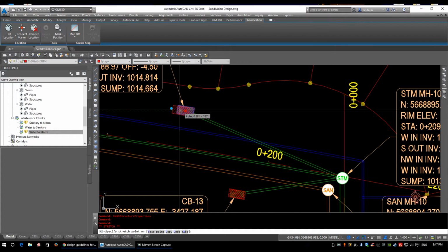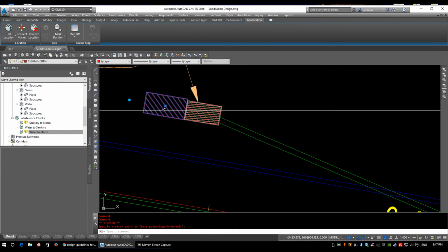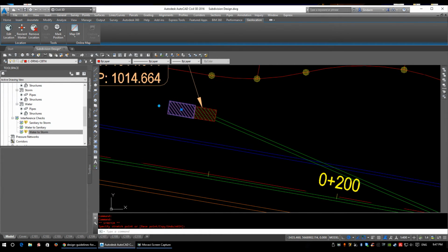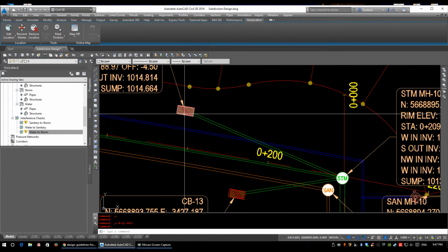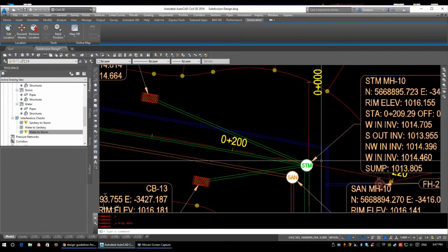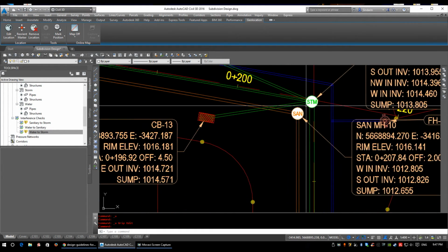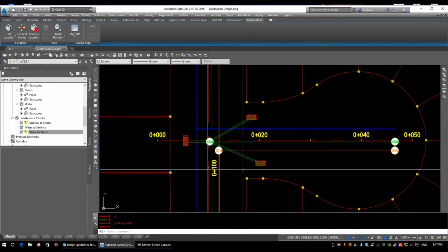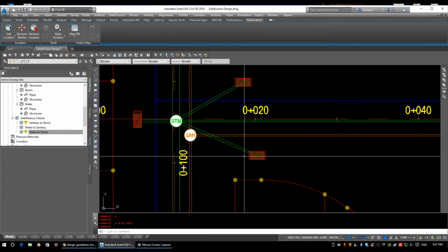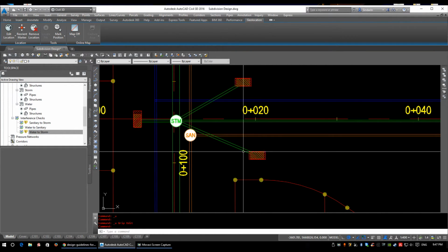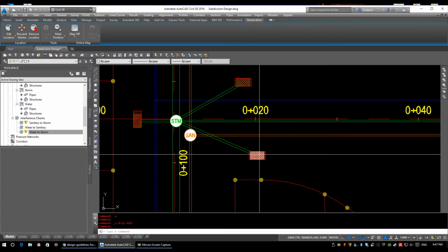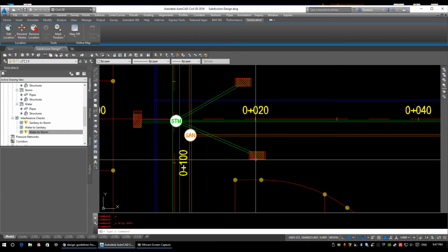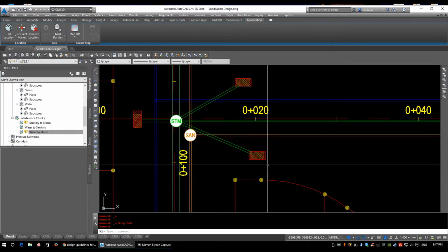If we were to say have a dual catch basin, so you have two catch basins beside each other, this outcoming pipe will be a 300 in that case. But we don't have any dual catch basins, we just have single, so we'll be connecting them into our manholes that way. Now when you come to places down here, you may have pipes running through your structure that will need to be adjusted. So we're going to have to move catch basins to allow the pipe to go around our manhole. We cannot curve these pipes, they are a straight pipe.